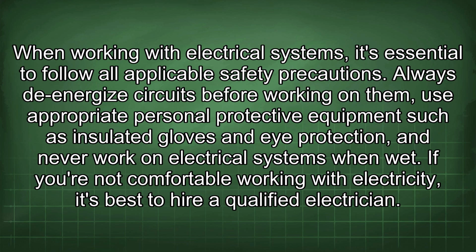When working with electrical systems, it's essential to follow all applicable safety precautions. Always de-energize circuits before working on them. Use appropriate personal protective equipment such as insulated gloves and eye protection, and never work on electrical systems when wet. If you're not comfortable working with electricity, it's best to hire a qualified electrician.